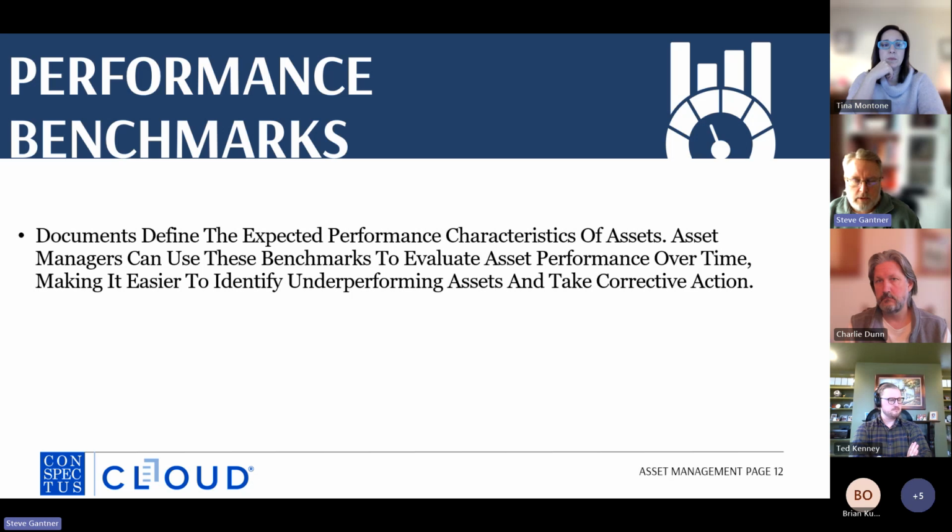Right. So when we talked about performance requirements, one of the key performance requirements that you might want to have included is, let's say it's supposed to flow at 1,000 gallons per minute. Well, in the performance requirements, you want to know a variable so that when your facilities group is monitoring that pump, if it fluctuates, what is the fluctuation allowed? Is it plus or minus 5%? What happens if it goes over? What should you look at? You can put that information in here. If it goes under, what should you be concerned about, or what should you be looking at?